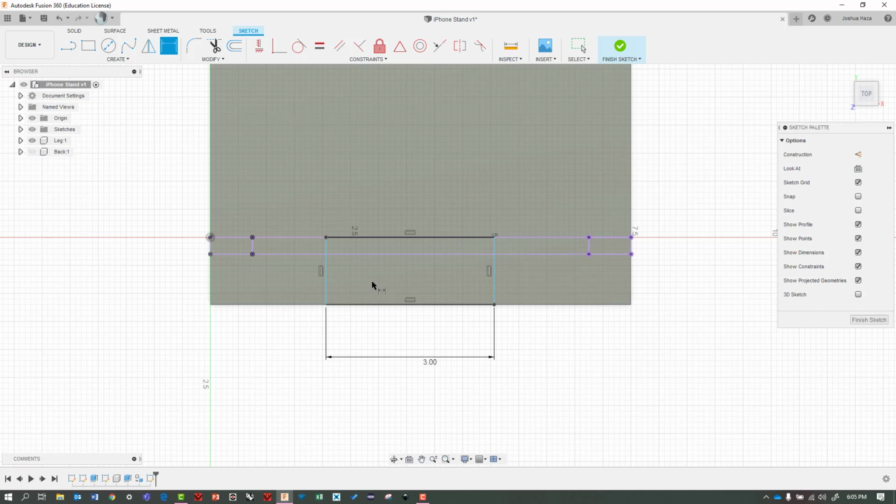So what I'm going to do is I'm going to center it. I'm going to use a constraint. So constraints are sort of things that set certain values to be the same. This time, I'm going to use the midpoint constraint. That'll line up the midpoint of 2 objects. So I click here, and then I need to click the 2 things that I want to midpoint. Notice the little triangle on my cursor. I want this line to be in the middle of this overall purple line. So I'm going to click here, and then I'm going to click here, and it's going to scooch it over and put a little triangle here, letting me know that it's midpointed between these 2 things, and now it's right directly in the middle.